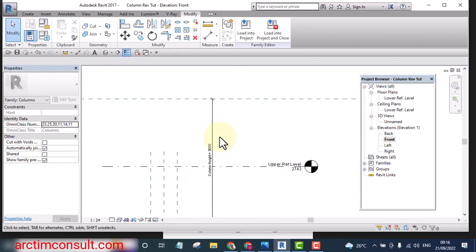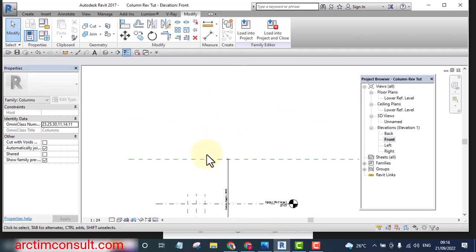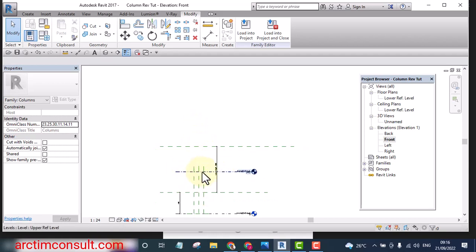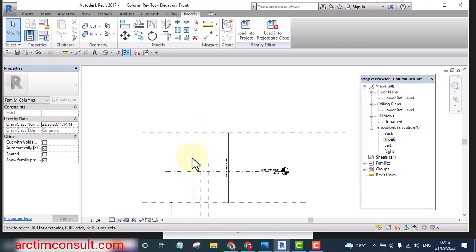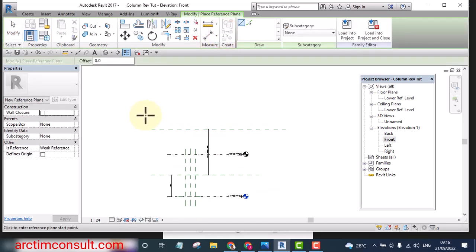If that is settled, and this is the adjustable height, it means that the capital will be above the adjustable height, because we don't want any design within this adjustable height. If you put any design within this adjustable height, it is going to scatter when you are adjusting the height. So our capital will be somewhere above the adjustable height.